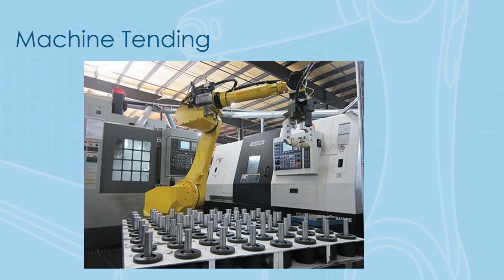Okay, machine tending. And machine tending is getting a lot of buzz now, and somewhat has tracked the buzz around collaborative robots. In this case, you'd always want to use an articulated arm. Machine tending, for most of the applications, all the ones that I've seen at least, the robot's going to have to reach in and out of some kind of cavity, whether it's a CNC machine or an oven or some other kind of process where you have to place a part inside of an enclosure. The articulated arm, based on the geometry of it and the way it's able to reach into things, is very well suited for this. So if you have a machine tending application, most likely you're going to use an articulated arm because of the geometry.